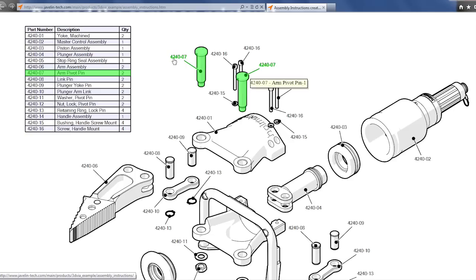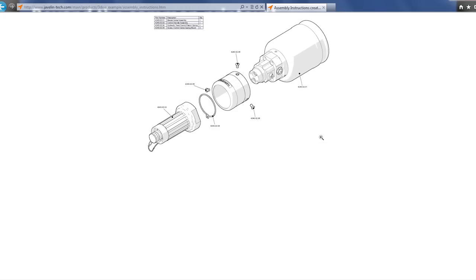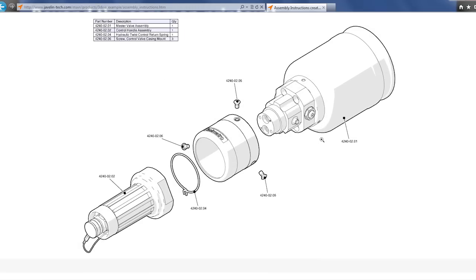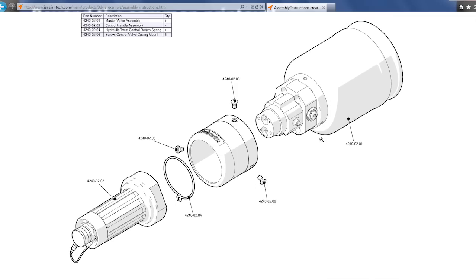Now, this document is also interactive, so 3DVIA Composer gives you the ability to link one document into another. So now you're seeing that we're working all in HTML. In this HTML document, I've got this vector line art image embedded straight onto the website, and this is all created push button straight out of 3DVIA Composer. And again, you'll see that same functionality of being able to hover either over the bill of material line item or use the graphic image to highlight the bill of material or the part out of the parts list for you.